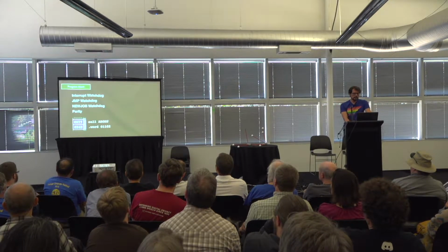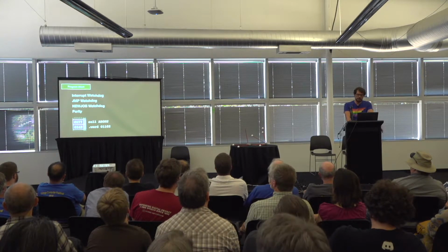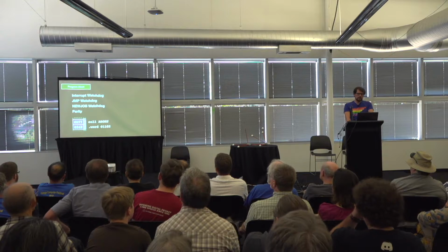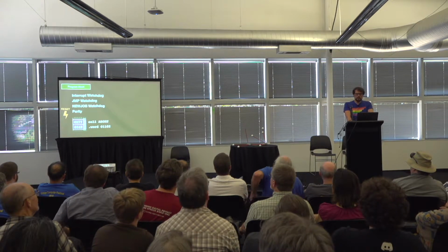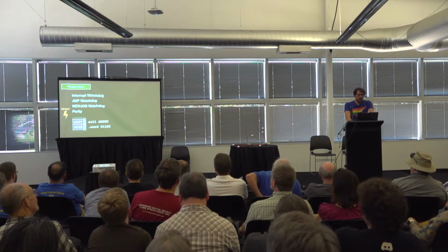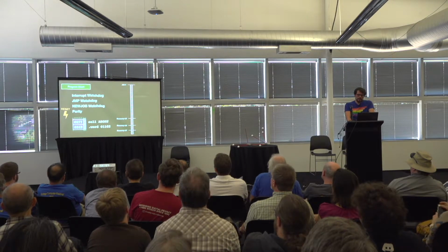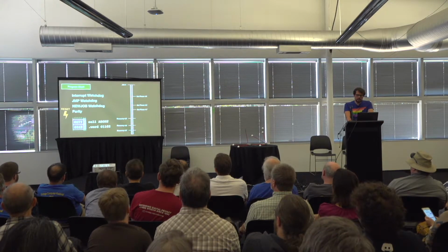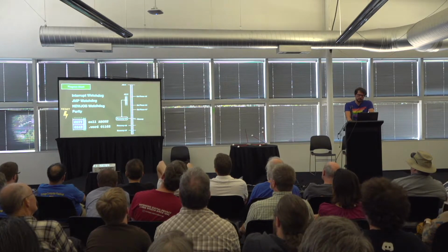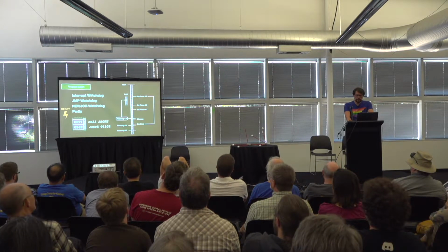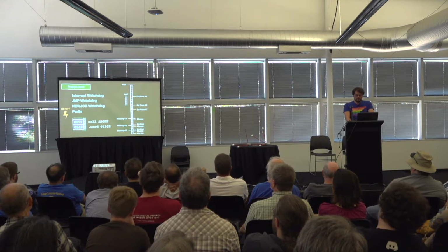Some kinds of failures triggered by various hardware watchdogs or by code make it impossible for normal operations to continue. In addition to showing the error code, they also cause a hardware reset. But the system software offers recovery services. A job can have a recovery code for its different phases. During execution, it sets the respective phase, and if an abort happens in any job or task, the currently set recovery routine gets executed, which could, for example, clean up and try the work again, skip to a different phase, or cancel the job altogether.